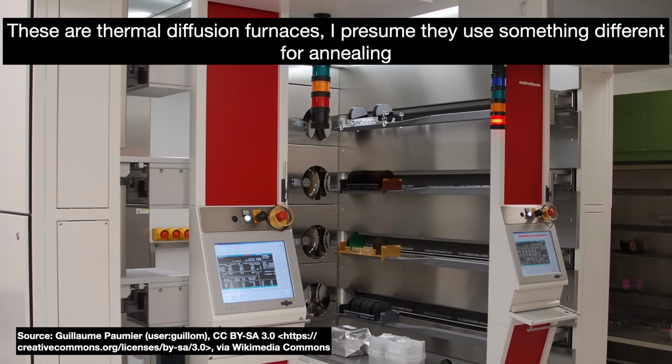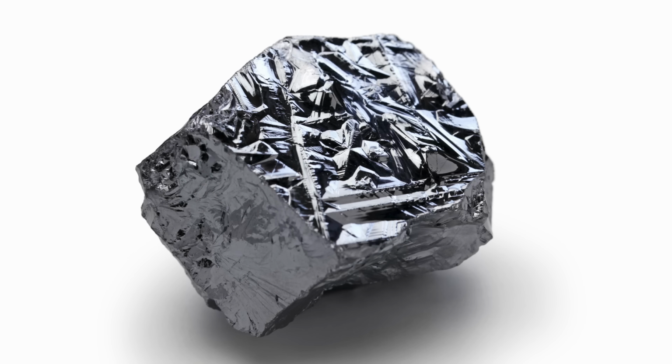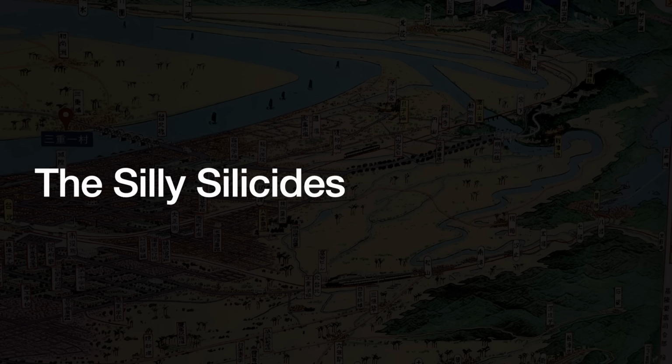This high heat is why we do the dummy gate. The real 45 nanometer gate is made from metal and would literally melt at those temperatures. But polysilicon's melting point is 1414 degrees Celsius, so it survives. Next up, we are starting to deal with the contacts. The transistor is coming together. Don't worry about the NMOS, we will get to it later.